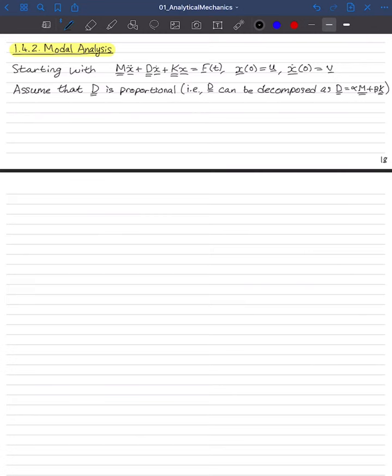We're going to go through a worksheet to define when a damping matrix is proportional and when it is non-proportional. In the case of it being proportional, you get nice real normal modes. In the case of non-proportional damping, you end up with complex modes. And I mean complex in the mathematical sense, that you have real and imaginary parts.